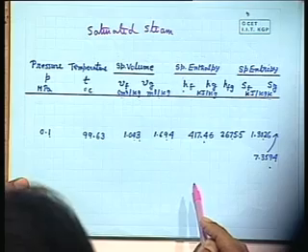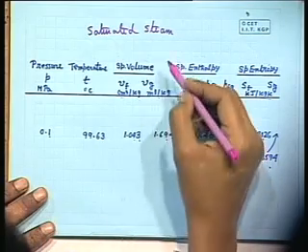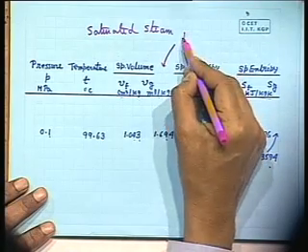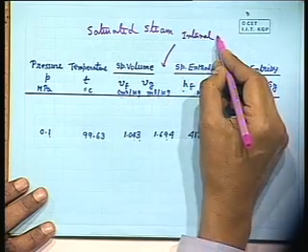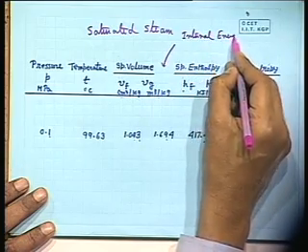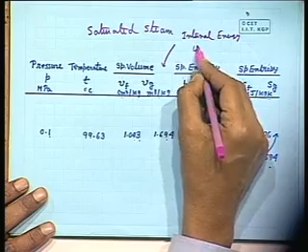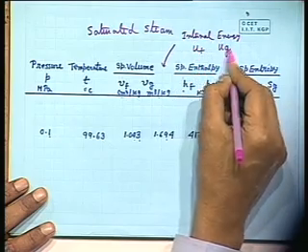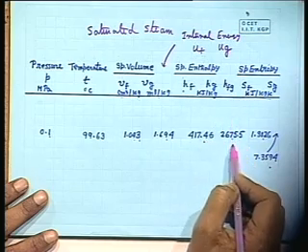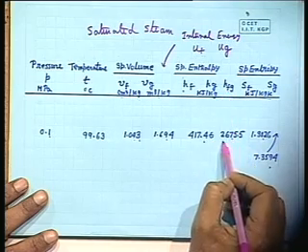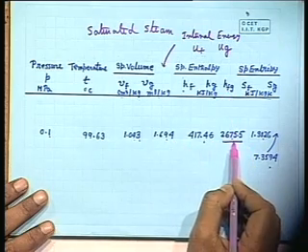oh, one thing is missing. I am sorry. What is missing? Internal energy. Very good. Because this is such a short paper, I forgot to write internal energy. Similarly, there will be Uf, Ug. Sometimes in many steam tables the difference is also written. For example, hfg. hfg has a very physical significance, that is the latent heat.